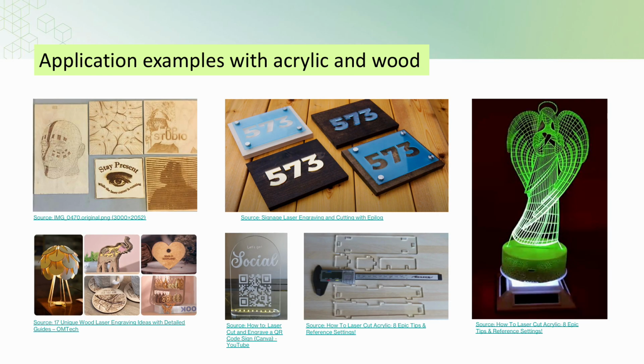These are examples prepared by laser cutting or engraving. Laser engravings are used to put drawings on pieces of acrylic and wood, then cutting is applied to take them out. Laser cutting can also be used to cut out parts to be assembled to form a model. Since the laser beam has a radius, margin will have to be given in the drawing so that the parts can fit with each other tightly.